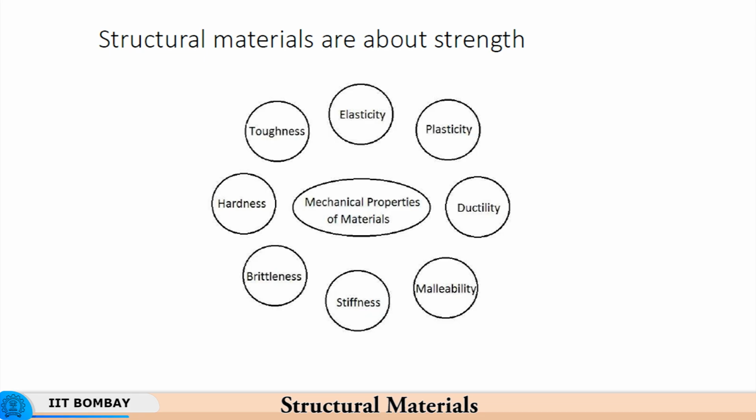amount of strength. It has got ductility, it is capable of taking a lot of permanent deformation, plastic deformation, but it is not very tough because it does not have too much strength, it does not require too much load for the deformation. On the other hand, a material would be extremely tough if it has strength as well as ductility. So, a lot of energy is absorbed by the material as it deforms in a plastic manner to a permanent shape.